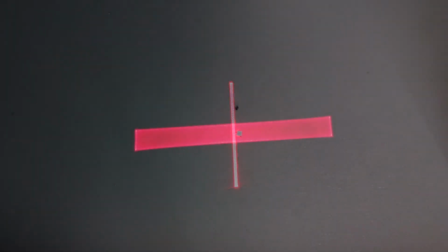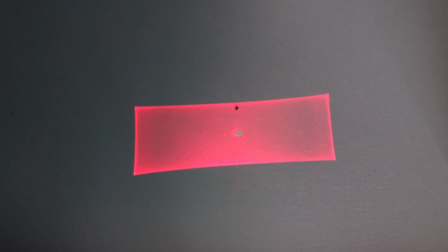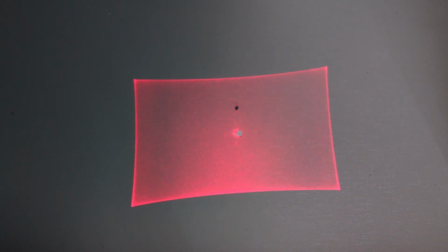If instead we drive the mirror along its fast axis, at its resonance frequency, we can see the projected pattern at 21 kHz. Also in this case is visible in the corner the mechanical movement of the structure. Finally, we can drive the mirror to make a full 2D image if both axes are actuated together, obtaining a raster scan projection. Thank you very much for your attention.